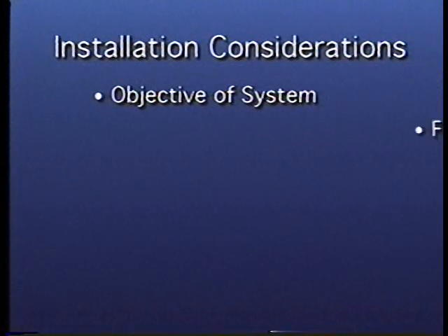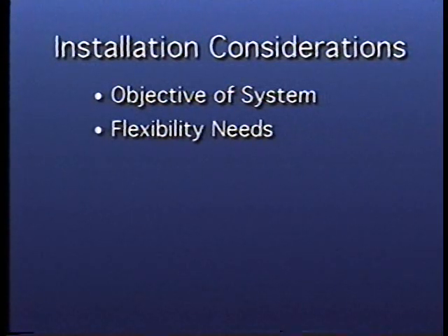Next, you should consider what type of flexibility must be built into the system to enable it to respond to changes in building layout. For example, how often are partitions and ceiling changes likely to occur? Frequent changes in layout are common in retail establishments. If that's the case, the practical solution is to supply the sprinkler system to individual tenants using a loop from the service corridor. Valves can be provided or installed by the tenant off of the loop to their individual space. Each of these valves should be supervised by the building's fire alarm system.